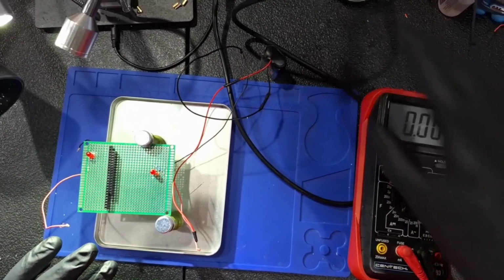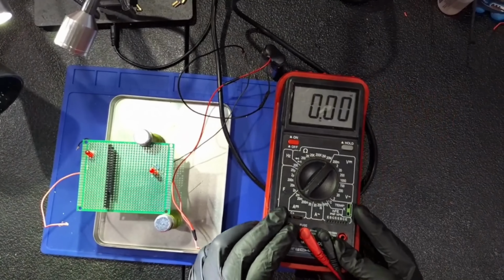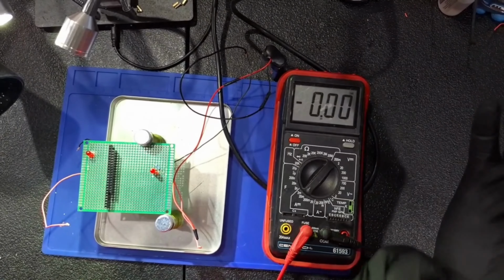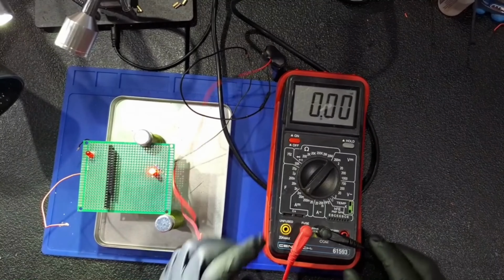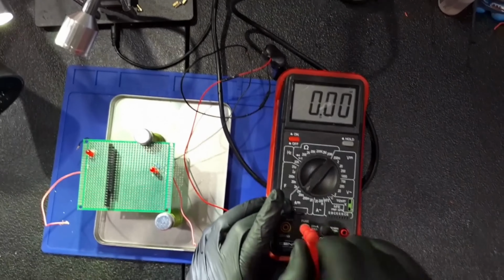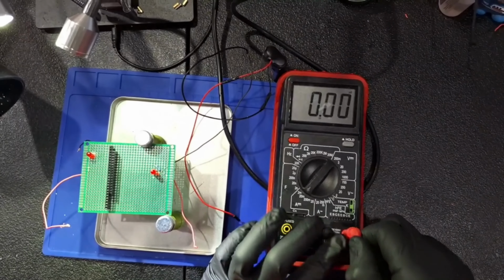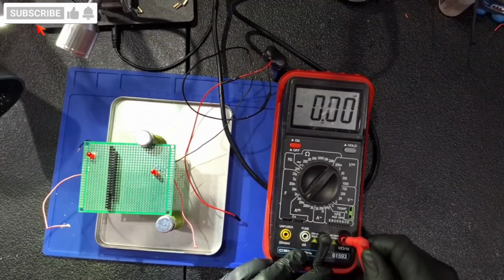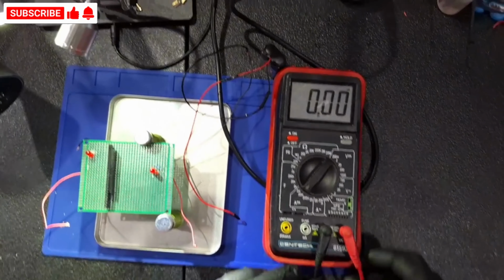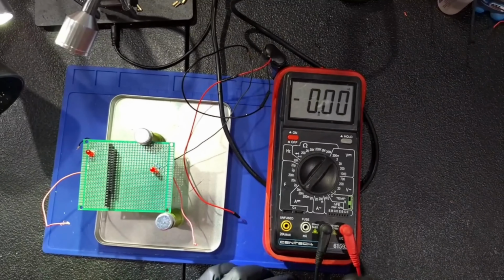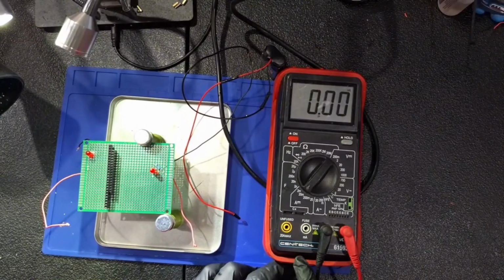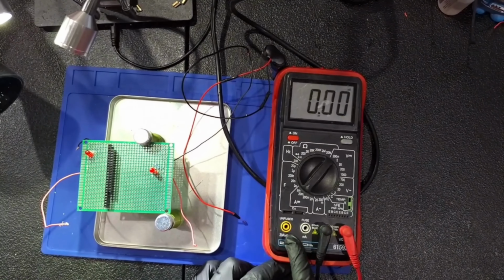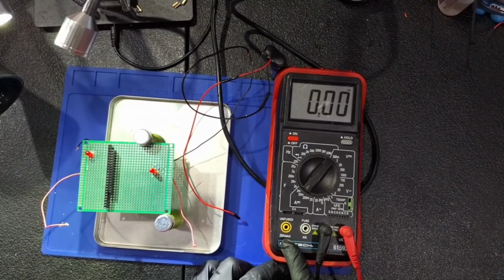So I understand that to test current, you break the circuit by removing the positive side from the source or from the battery and connect it to the red probe on the multimeter. Also, the multimeter should be connected into the fuse connection, into the milliamps or the amps connection, and not in the volts connection. So removing it from the red connection that's marked volts and ohms for testing, we need to put the red probe into the white or yellow probe as seen on my screen here.